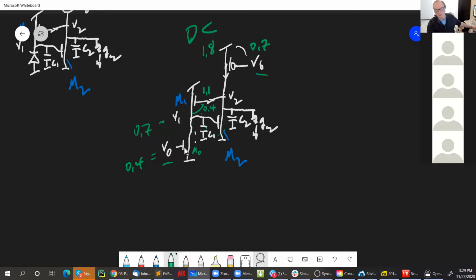So with practice, you can do other stuff like that. You can do it for a transconductance amplifier, a wide range transamp. If you want to be well prepared for the exam, this should be effortless. And you make all the simplest possible assumptions. You always assume kappa n and kappa p are both 1, that I0n equals I0p, and that W over L is the same for all the transistors. Just make it as simple as possible, because it's just about reasoning about these VGSs. Okay, so we're in agreement that we can reason about the DC level.